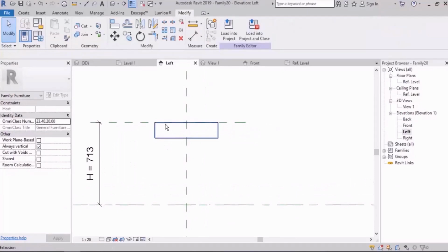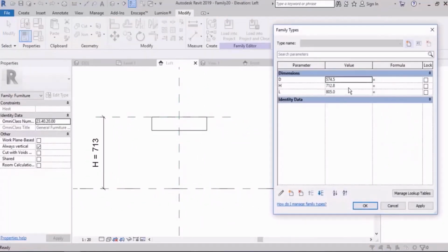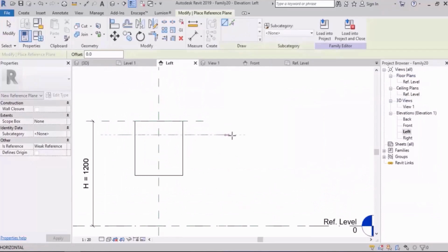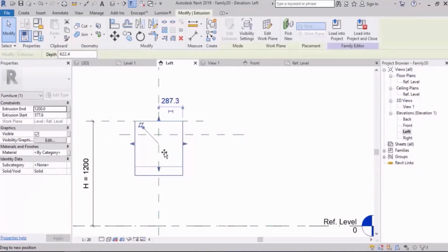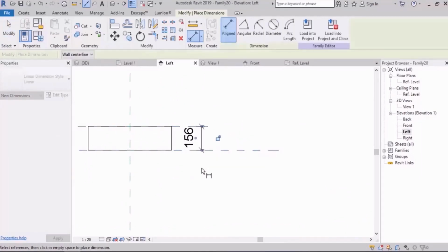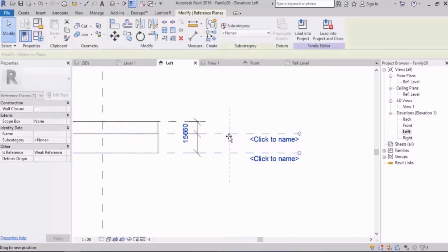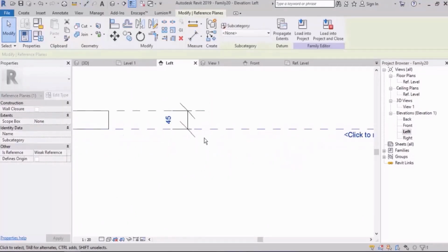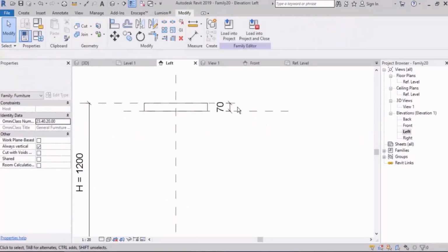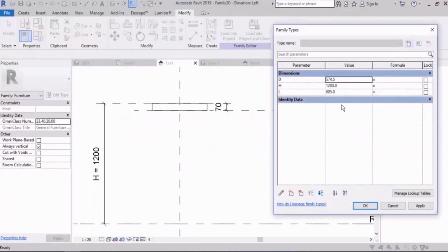But you surely know that the thickness should be controlled, unless when you increase the height, this happens. So I pick a reference plane as the representative of the lower part. I stick it, lock it, and now if I want this part to be parametric, all I've got to do is to measure the distance and give it a parameter. Also, I said that for not doing too much, it has a dimension, just lock it. The height, for example, 90.